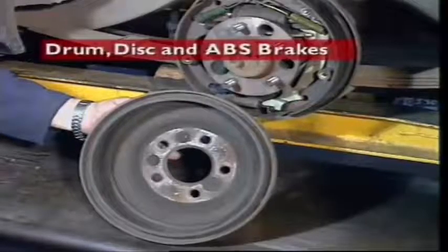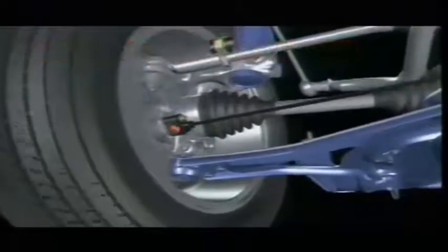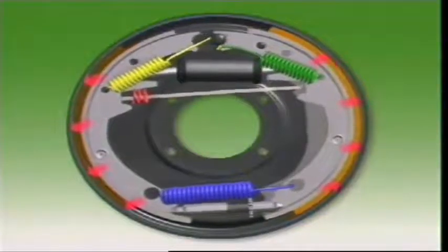This section examines drum, disc, and anti-lock brakes. Drum brakes have a drum attached to the wheel hub, and braking occurs by means of brake shoes expanding against the inside of the drum. With disc brakes, a disc attached to the wheel hub is clamped between two brake pads.